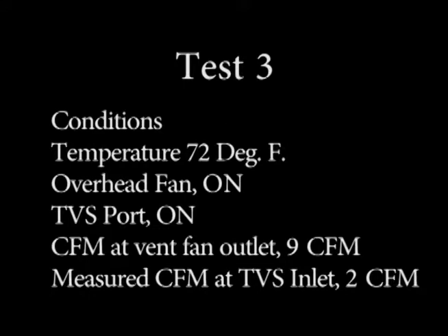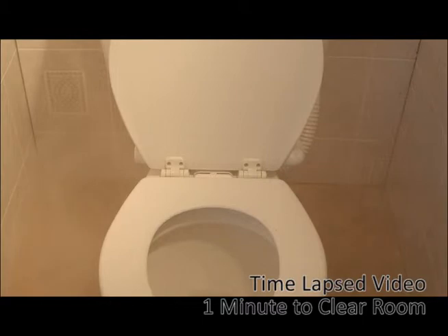Test 3. Test 3 simulated the condition where the ceiling fan and the TVS system were both connected and operational. The system used the same fan to simultaneously evacuate both the ceiling and the inlet port of the TVS system. The test smoke entered the test chamber through the toilet bowl. It first filled the bottom of the toilet bowl. The visible constituents of the test smoke vapor boiled in the toilet bowl with a small amount of smoke overflowing and filling the area near the floor of the toilet.